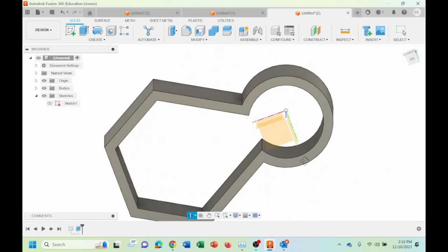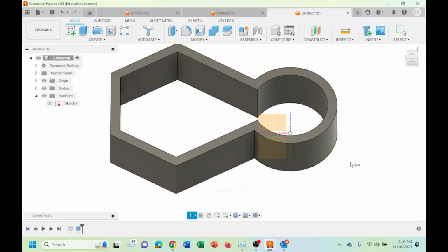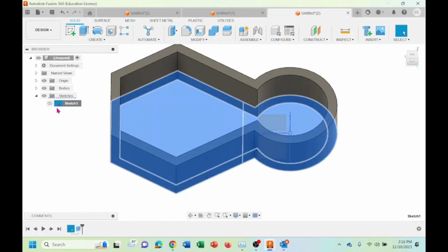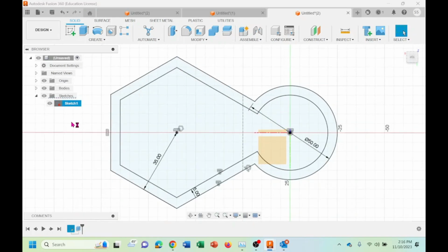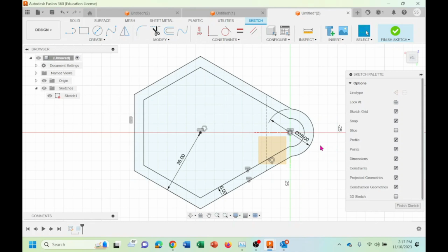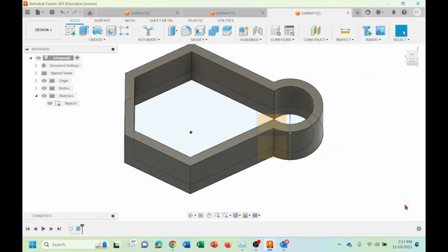So you could go to the orbit and see this is a cool design that you have. Now the question is, is this design solid? We will see. We go back to the sketch level. If you want to change some dimension here, if you have a solid model, no matter what you adjust, the whole model should adjust itself. I'm changing to 25. It adjusts everything, but it's too much. Let's say 35. See, it is adjusted. It doesn't matter what you are adjusting, it adjusts the whole model, which tells you it is a solid model.